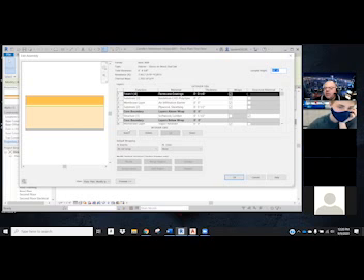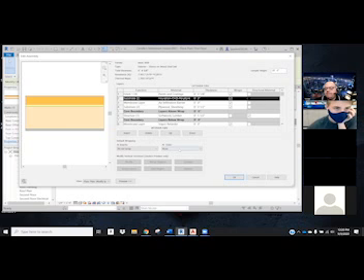And Victor, if you'll let me know when you have those set. Again, if you need to add in the finish of the substrate, use the insert button and use the move up and down to position it where it needs to be. To select a new layer, just pick the number and that highlights it. But if you let me know when you're done so we can move on, that'd be great.